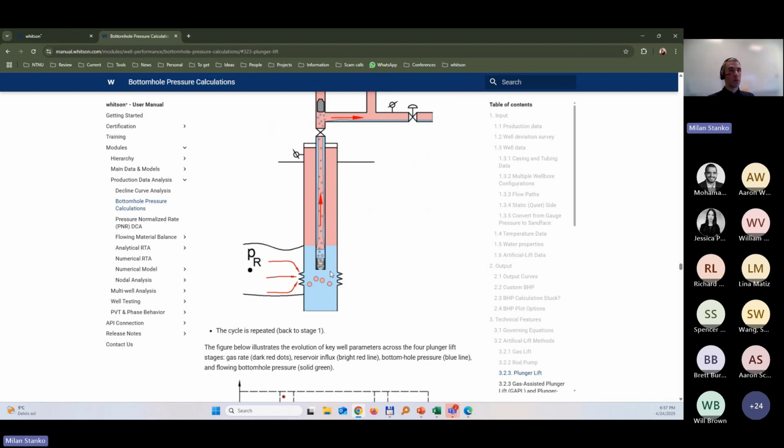So that's another option you have for plunger lift. And again, this liquid level measurement doesn't have such a high resolution. You have an average for the day, and that's the value that will be used, the average, although it will change during the plunger cycle.